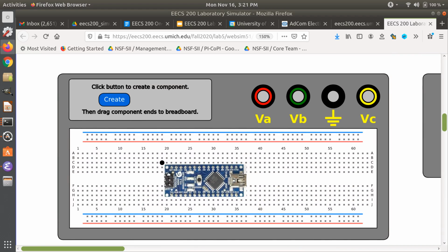So those are the digital in and out for the trigger and the echo functions of our sensor. And up here, if we read upside down, this is V in, this is ground, this is RST, whatever that is, this is 5 volts. So the 5 volts is what we care about, as well as the ground. Those are going to be connected to our sensor as well. So 5 volts, ground, D12, D11, and the USB connector here. That's all that we have to connect up. And we'll connect this last, because we shouldn't be connecting up all these other things with it powered.